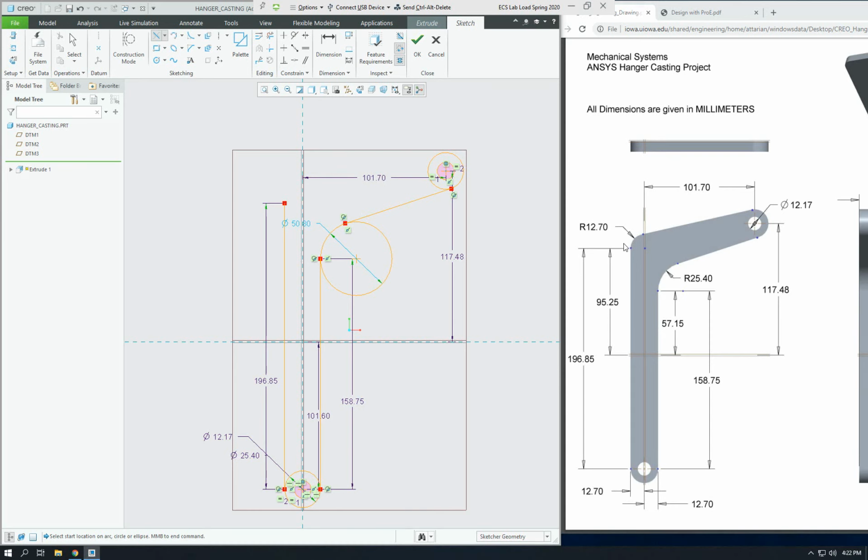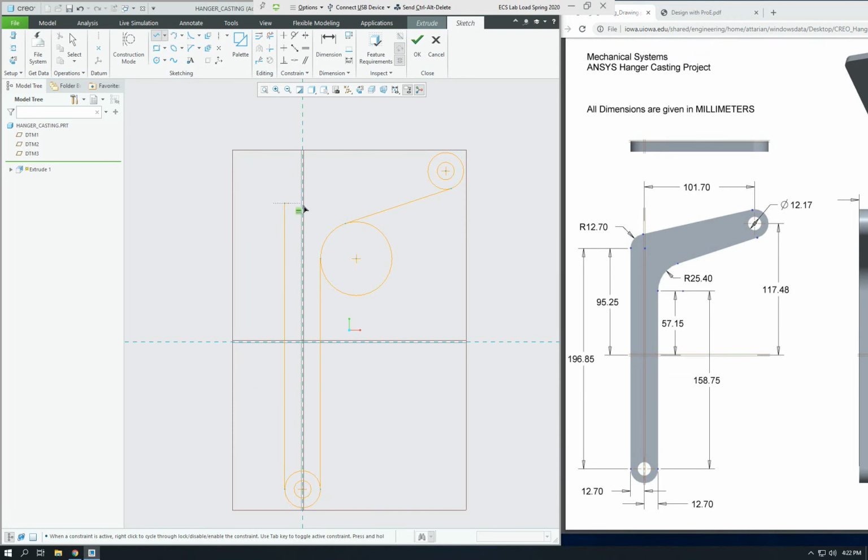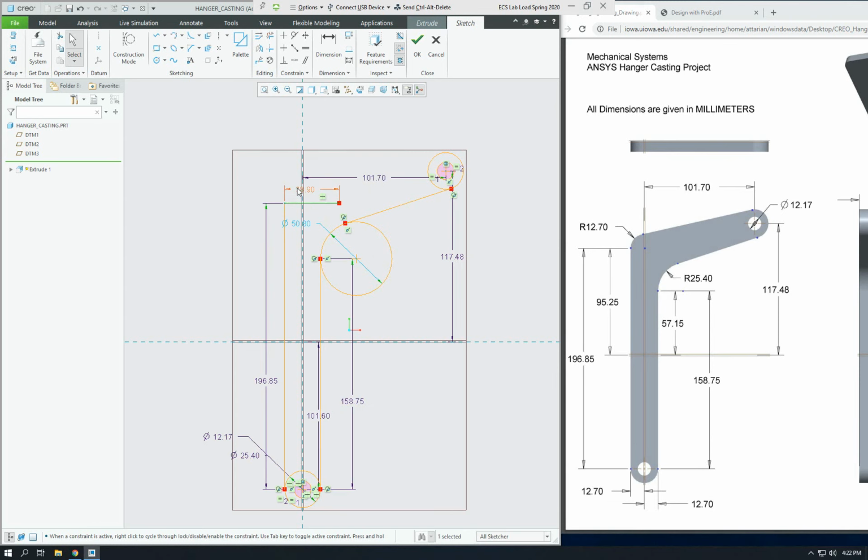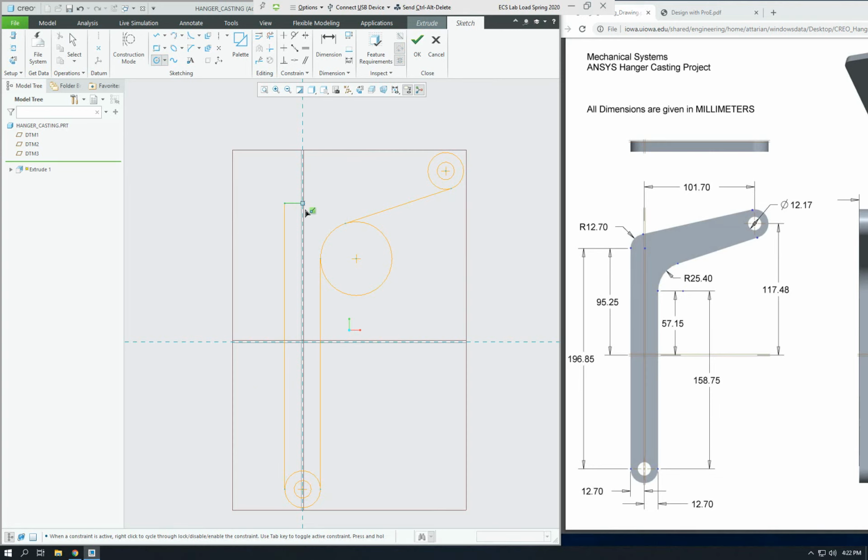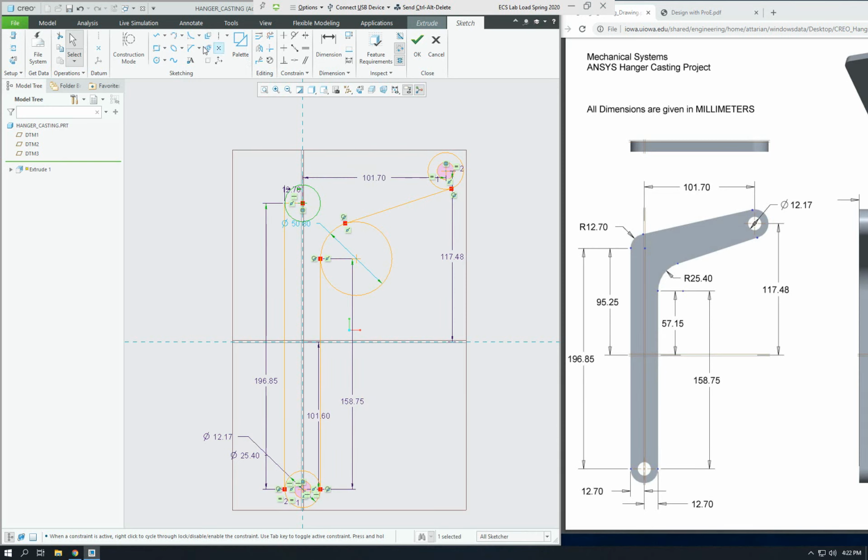And we can use the same trick for the second circle here, this half circle. To do that, again, line, some horizontal line, click, and since this is 12.70, I write 12.70, comes here, I come here, draw the circle, middle button, and then now I can draw that tangent line between this circle and this circle, and here it's finished.